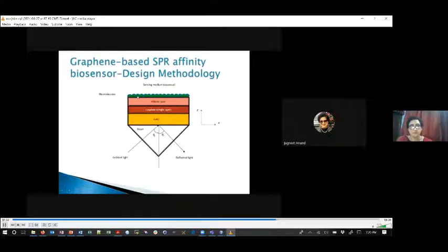And I would like to emphasize that this is actually an evanescently coupled device. A sensor is an evanescently coupled device, and the changes which are taking place in the biomolecule layer here within the penetration depth will be responsible for change of this angle theta I, at which the incident light is able to excite a surface plasmon mode at the metal interface.